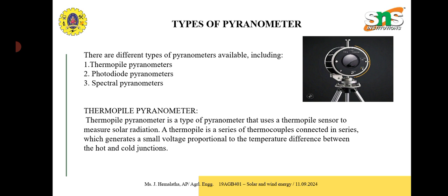The thermoelectric induction principle is used, whereby incoming radiation is almost completely absorbed by the horizontal blackened surface over a wide wavelength range. The resulting increase in temperature is measured by the thermocouples connected in series and parallel to make a thermopile. It is necessary to protect the black detector coating against external influences which may affect the measurements, such as precipitation, dirt, and wind.